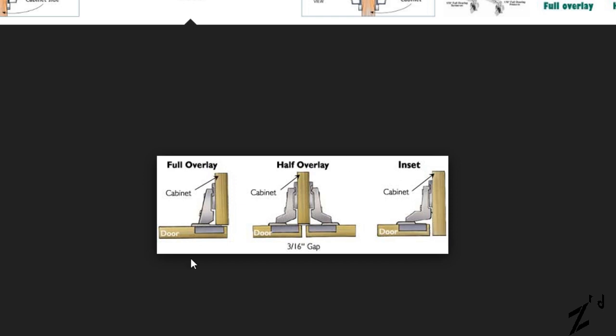Clip-on hinge is basically any of these. The idea is that it's easy to install. When I say easy to install, I don't mean the actual connection to the door itself. These things come as separate pieces, so you can have one carpenter fix the hinges to the door side completely, and the other guy do the support hinge everywhere, and then they can just carry the door there and snap fit it into place, or clip it on. There are issues with trying to do that. Obviously, you have to align it, so it's generally the same person doing it. But that's the reason it's called a clip-on hinge.